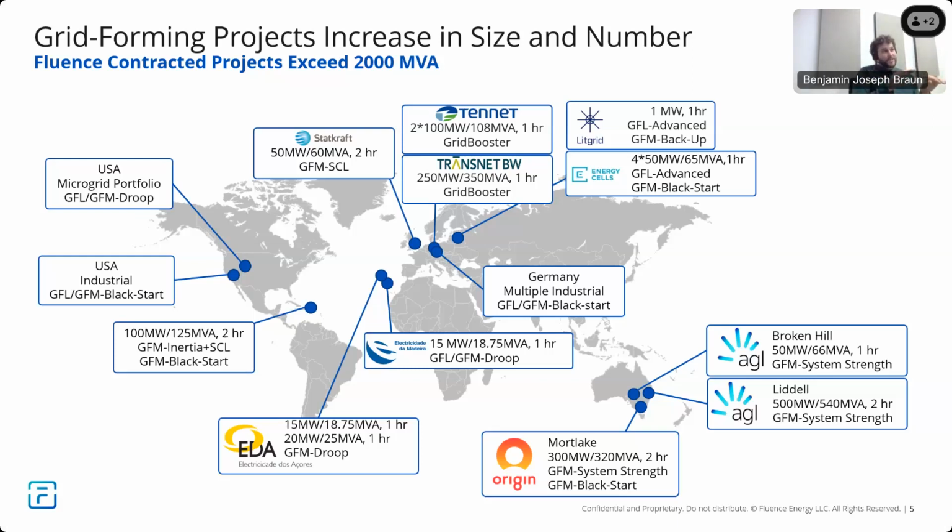Underneath all of these projects are some internal classifications in terms of what each is actually doing. So we had the Black Start projects, but is Black Start the same as just backup, where you're not starting a generator, but you are securing a load? Those are technically two different applications, very closely related, yes, but slightly different. You can have a co-located Black Start versus an external Black Start somewhere else in the grid. Again, similar, but nevertheless different enough that we have to approach them in different manners.